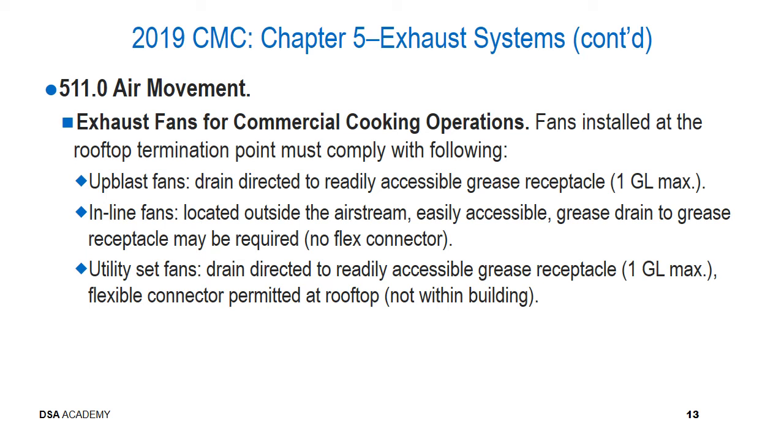So for commercial cooking applications where grease is a consideration, generally speaking, the fans are going to be installed at a rooftop termination point, and they have to comply with a couple of requirements. One of the main ones being that the grease that's going to be collected has to have some method for being drained.